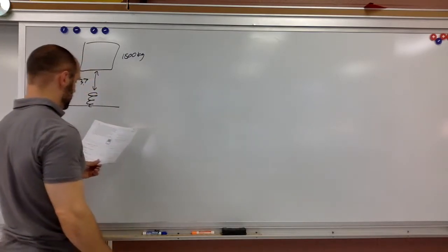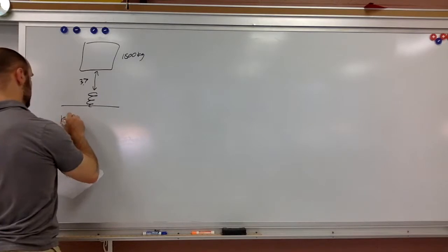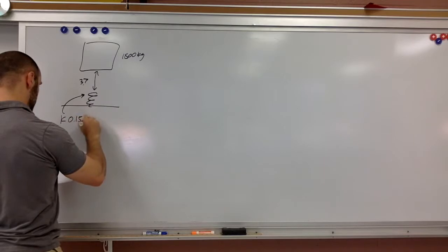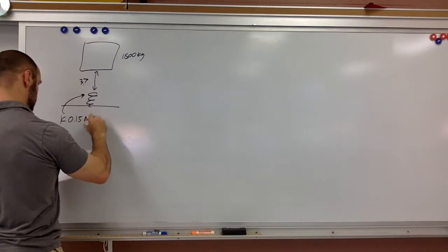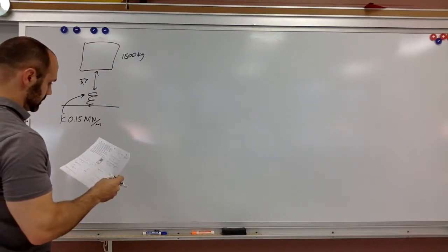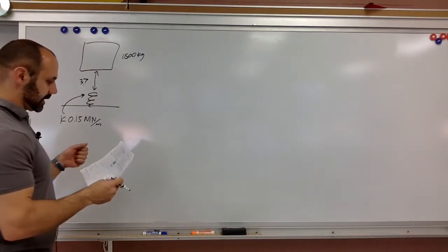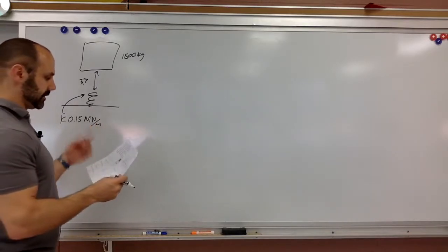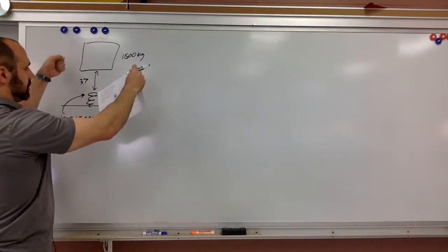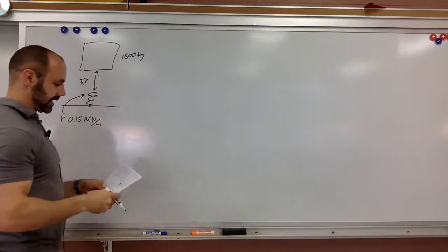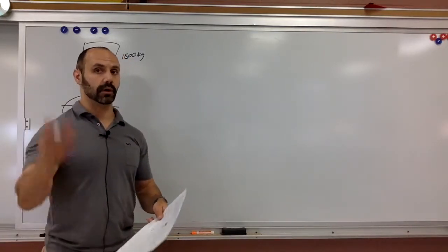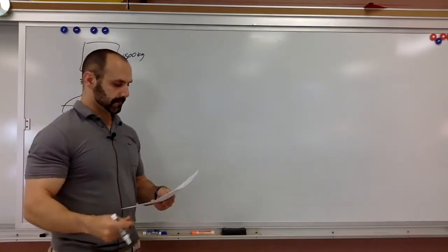That's important to know. And the spring has a constant, k, of 0.15 meganewtons per meter. And then the safety device clamps on the cab so that there's a constant force of 4.4 kilonewtons opposing the cab's motion. So the idea is that those clamps click onto these poles. So what I now have is a friction force of 4.4 kilonewtons, whether it's moving down or up, because we're going to have some bouncing going on.